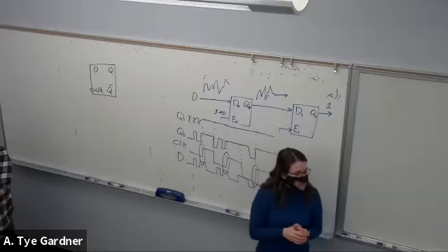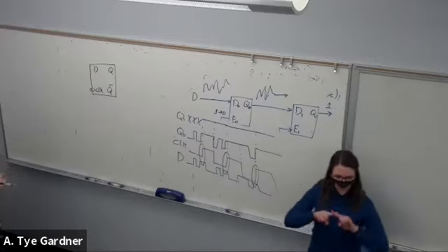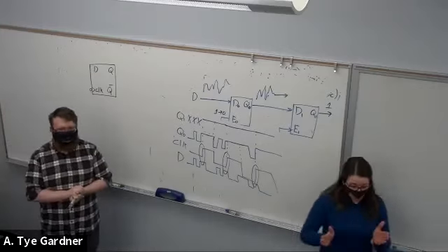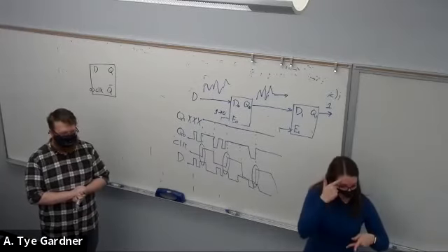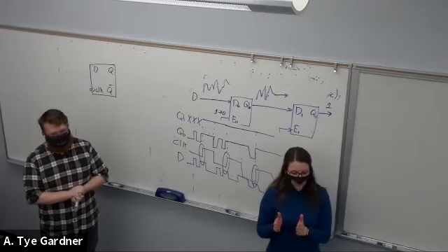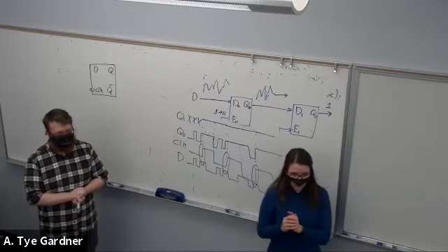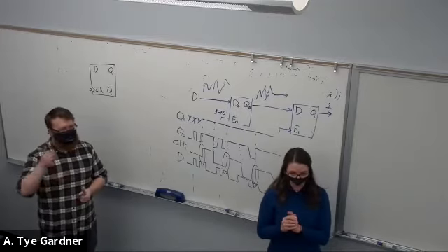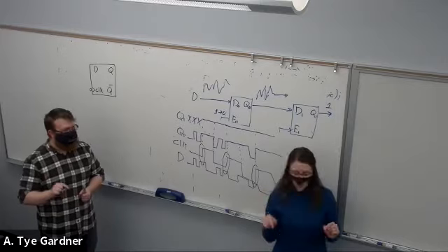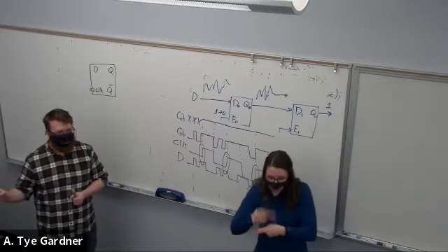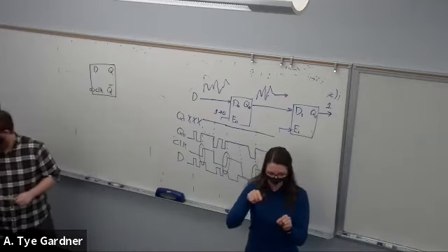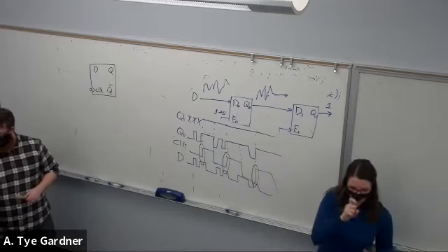Can I ask a question? Yeah. What is the difference between synchronous and sequential? Sequential refers to a type of logic that happens in order with memory, whereas synchronous refers to the fact that sequential logic is happening at the same time, predicted by the rising edge of a clock. So synchronous is a type of sequential logic. Okay.